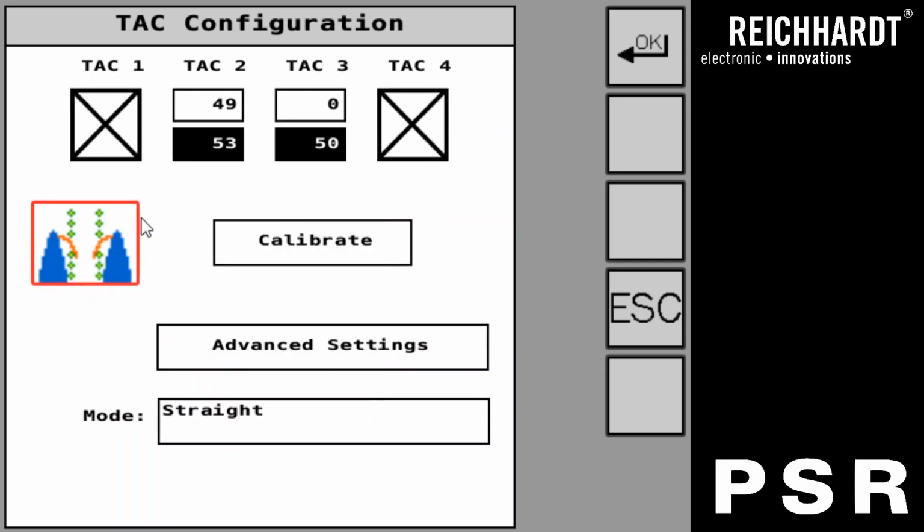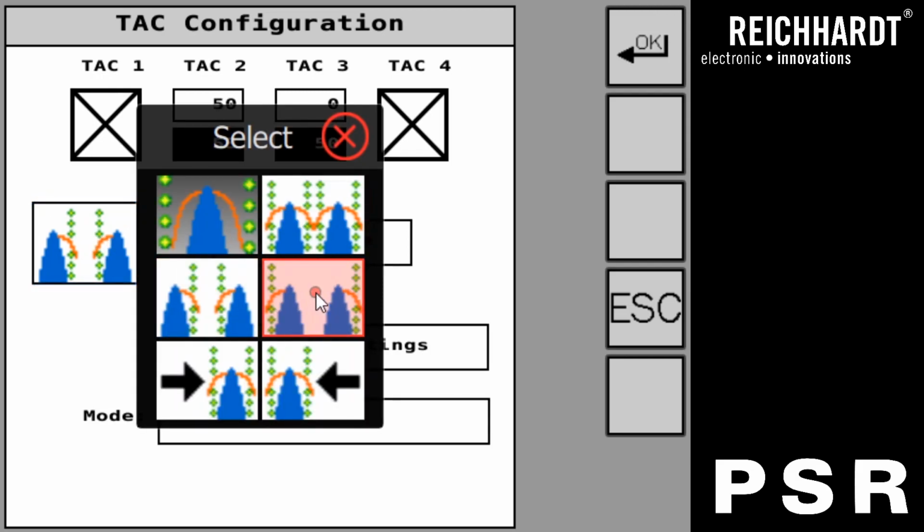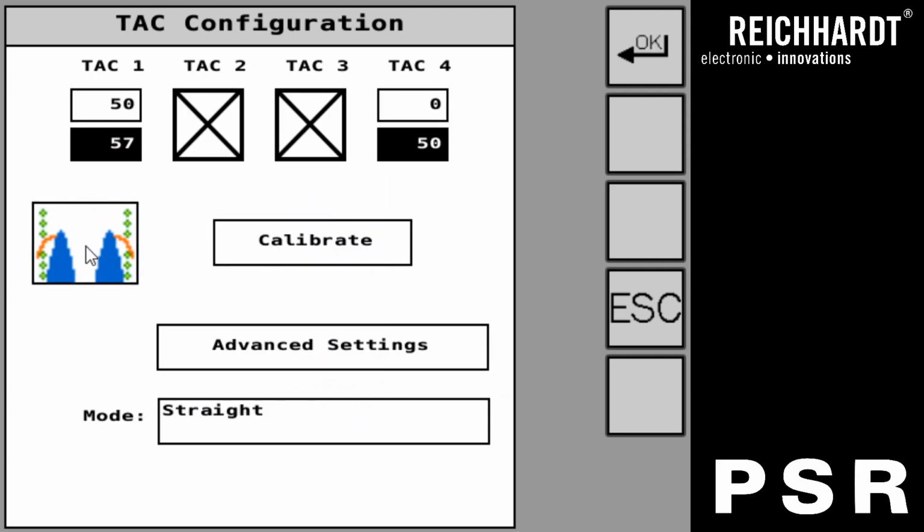We also have unique configurations depending on different patterns. A good example would be this one shown right here. We use this for markets like cotton, or if we have extra wide rows, 36-inch wide rows, we may put two TAC sensors in a single corn snout, reading the outside sensor from each. So then we're reading TAC 1 and TAC 4.